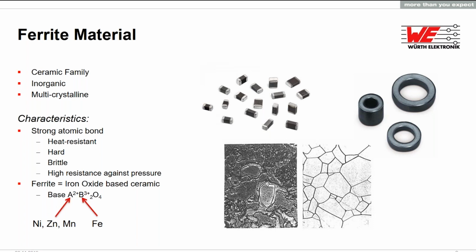However, if you drop your PCB or if you drop a ferrite ring core in general, you can see that they break easily. That's because they are brittle. Ferrite material is based on nickel zinc or manganese zinc, however, mostly nickel zinc. And it has the ferrite component or ferrite iron oxide component, which everybody knows more or less as rust.